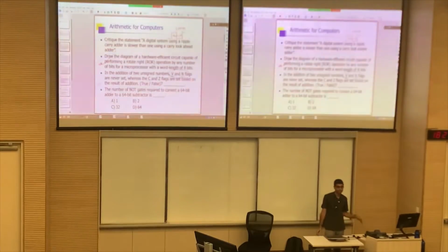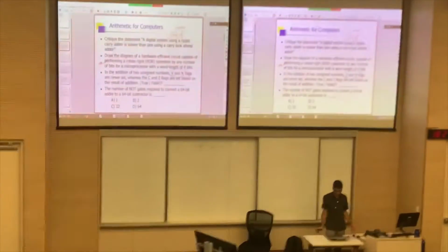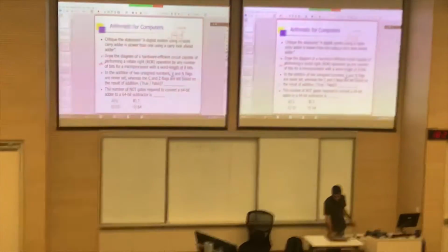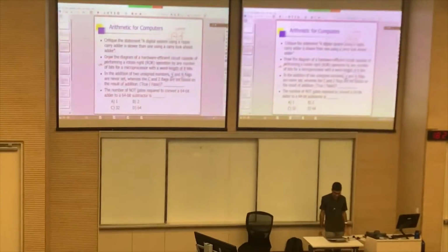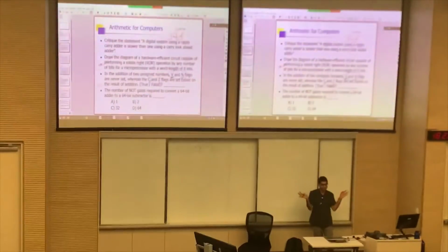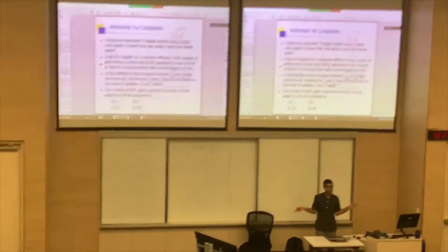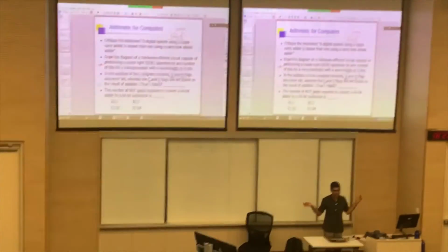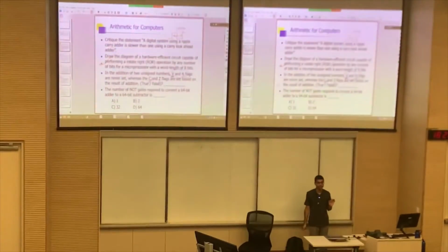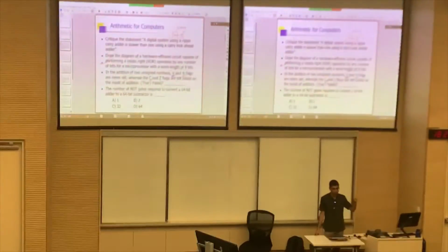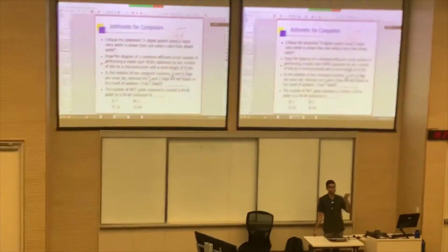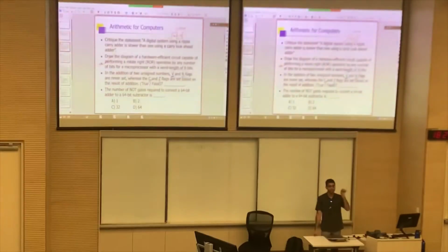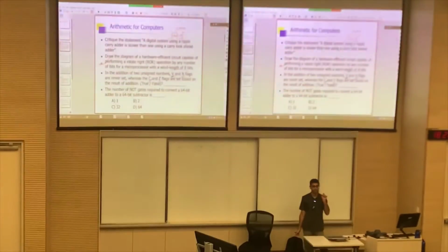And you could argue that the hardware is actually making an implicit assumption that it is dealing with signed numbers when it deals with V and N flags, and unsigned numbers when it deals with the C flag, and the zero flag is applicable equally for both. But that is just a way to look at it. In reality, the hardware doesn't really care. Hardware will modify N, Z, C as well as V as appropriate, and it is up to you as a programmer to decide which bits you are going to check based on your understanding of what number system you are using.